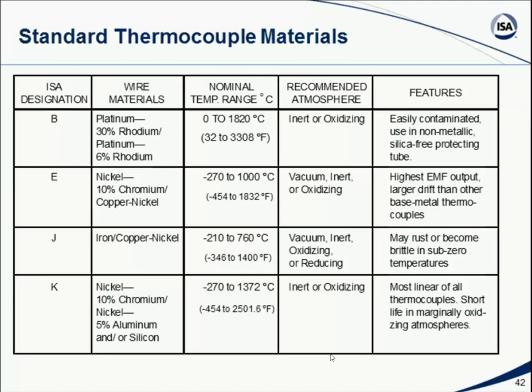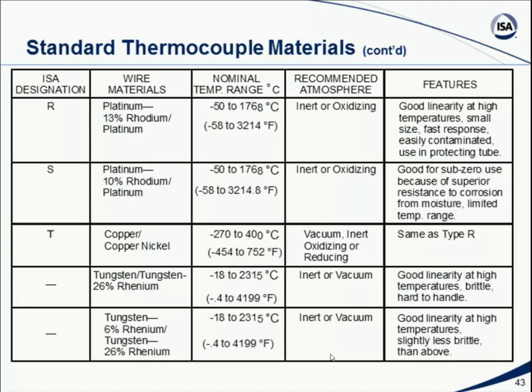So different types of thermocouples exist, with different characteristics as far as the voltage that they generate. When we talk about the voltage, we're talking about microvolts. In most cases, the voltage generated by a thermocouple is somewhere between about 1 and 70 microvolts per degree Fahrenheit. So we're not talking about large voltage levels. We're talking about hundreds of microvolts between the lowest and highest temperature range. But that is something we have the ability to measure today. So again, there is a wide range of devices based on different materials with different characteristics, which makes them good for certain applications because of their resistance to corrosion and their ability to withstand higher temperatures. And thermocouples are very commonly used as temperature measurement devices. For one thing, they're fairly rugged.